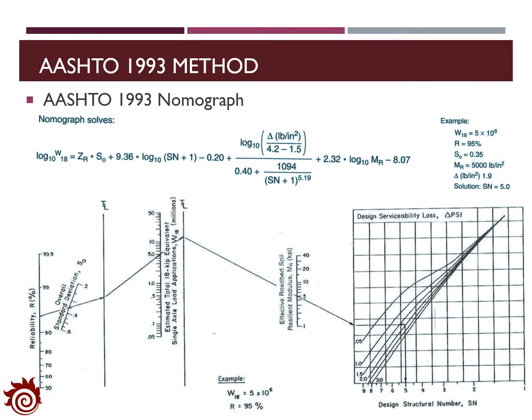Within all the steps in the design of the flexible pavement, the estimation of the structural number is one critical step. Actually, the estimation of SN can be conducted based on the nomograph, which is shown in the figure here. The implementation of the nomograph is quite straightforward. Now let's check one example to see how we can use the nomograph to find out the value of the structural number.